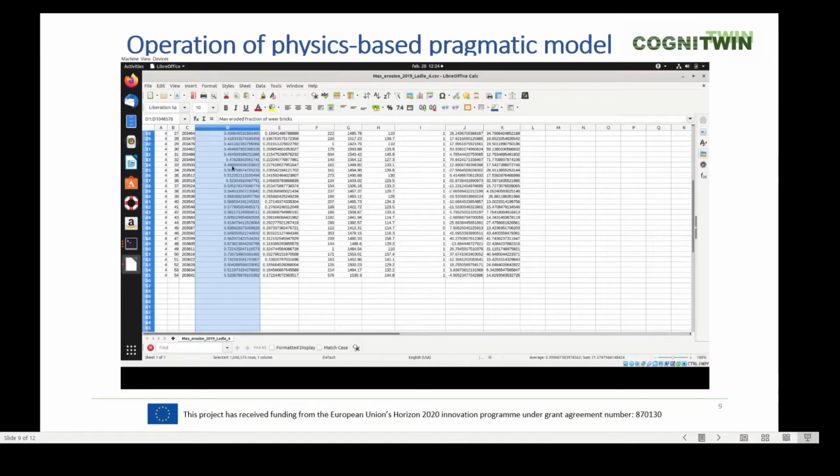So we can see here that after some 51 uses, we are hitting the 75% limit. And at that stage, the ladle will be repaired. But only the upper part of the ladle is repaired. The lower part is not repaired because erosion is generally smaller in the lower part.